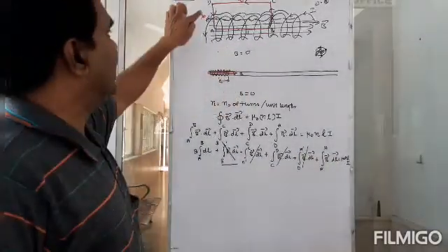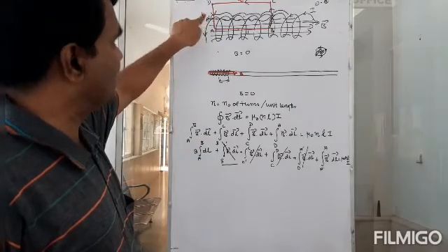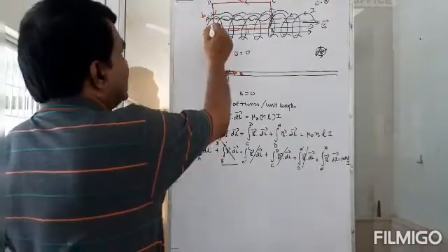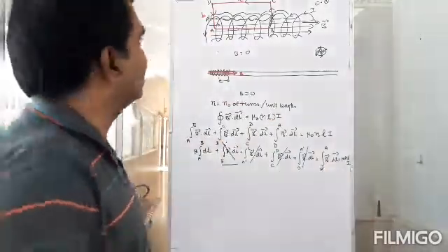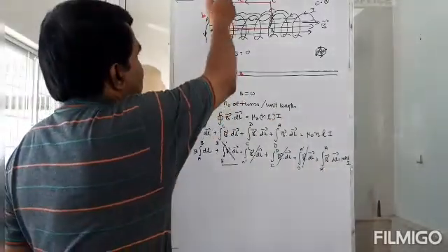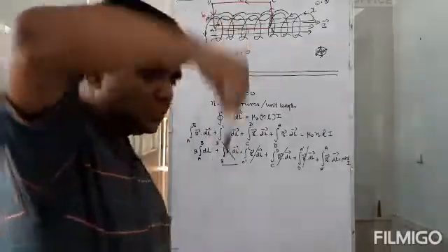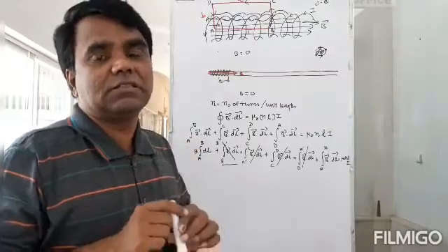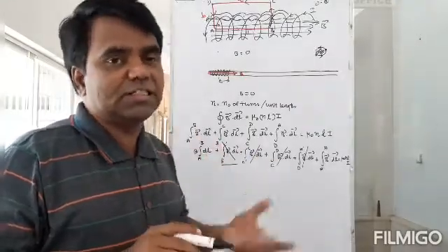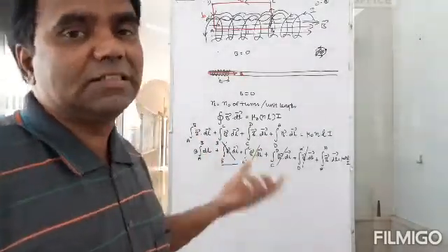And A dash to A, well, you will have B here anyway. B is not 0 because you are inside that path. But then the DL is perpendicular to B, so the cos theta value will become 0 because the angle is 90 degrees.